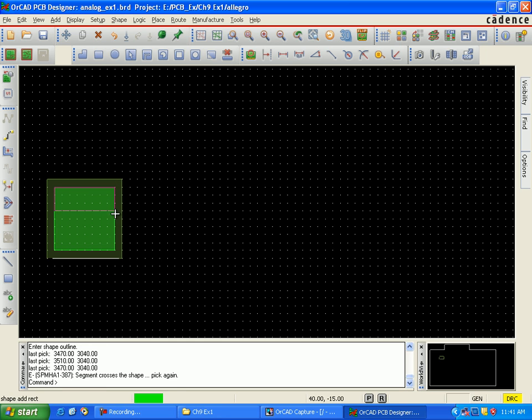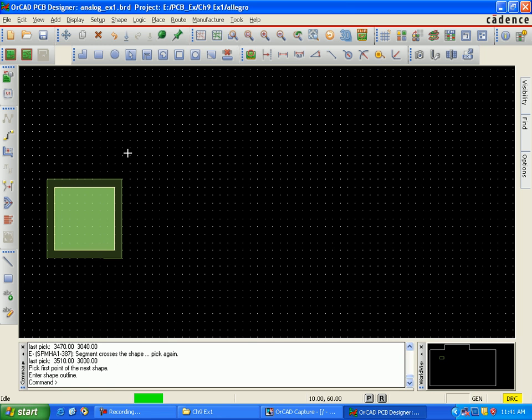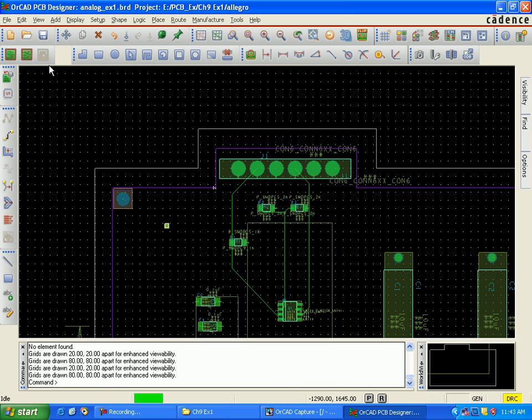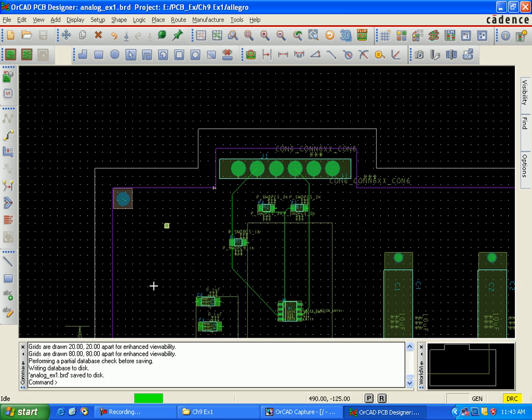The inside green will be the solder paste and the outside one the solder mask. So once you make one patch, you copy and paste it at each and every SMD component. So this one is the one patch we make.